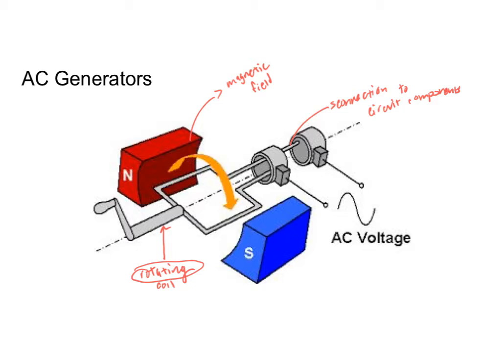So these are the general components of an AC generator. And when we're talking about alternating current, instead of a DC current, which is going to be some constant voltage, what we are looking at is an alternating voltage. So our voltage is going to have maximum and minimum EMFs over time as the coil rotates and as it moves in relation to that magnetic field. So the more coil that is perpendicular to the magnetic field, the larger the magnitude of our EMF.